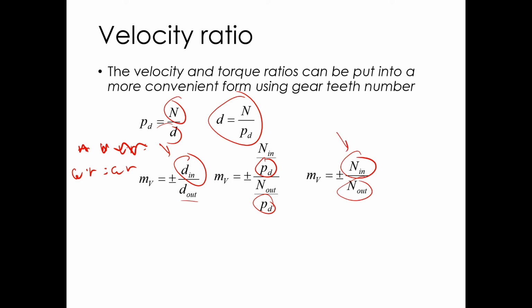So now, I don't know what it is about counting teeth on gears, but you always miss one or two when you count. Especially on a gear that's got like 50 teeth on it or something. I've never counted teeth the first time and got it right. It always changes after I count it 2 or 3 times. So I don't know what to say on it, but mark a dot to start with when you're counting teeth.